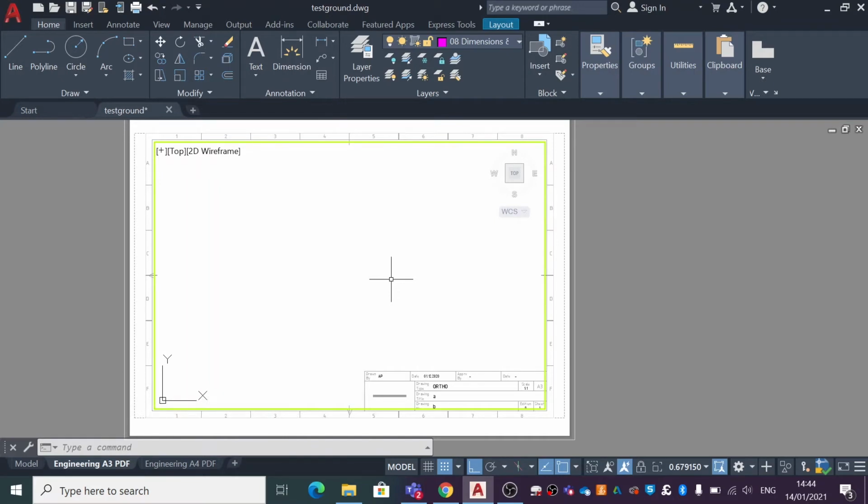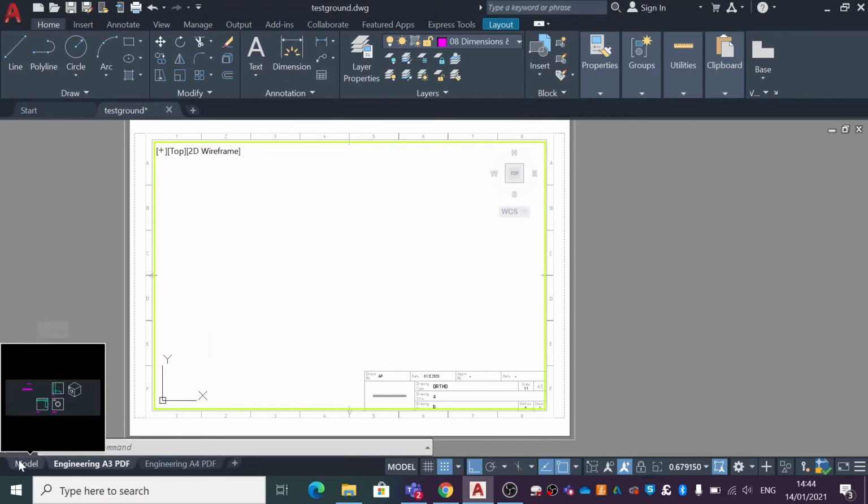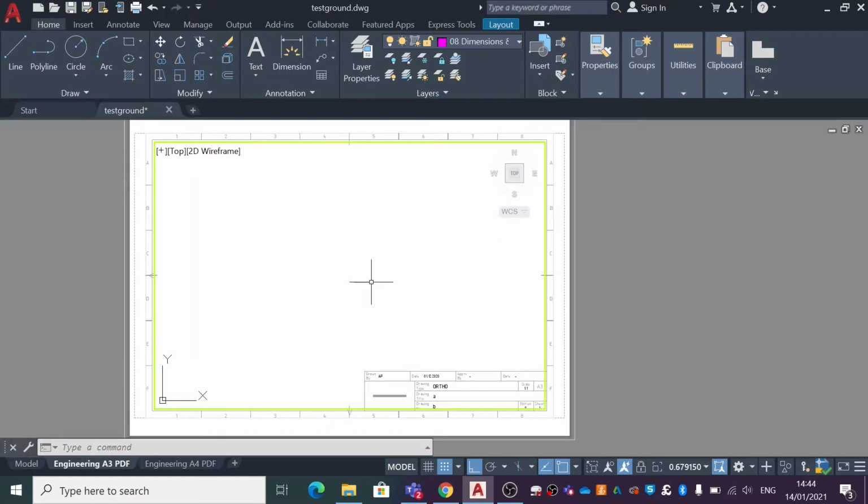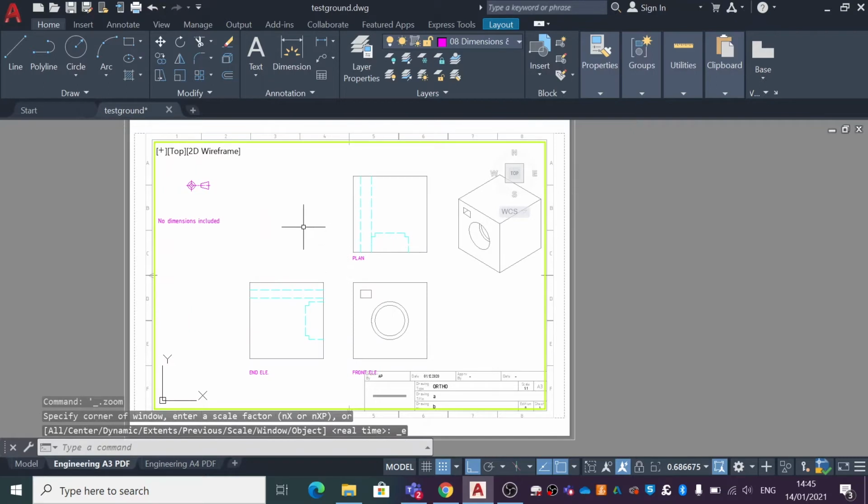Now when you're drawing things in the model space over here, that is an infinite space. Your viewport's an infinite space as well, so you may be tempted to try and pan around using the mouse wheel by pressing it down to look for your drawing, but you're not guaranteed you're going to find it that way. So how to get your drawing into the viewport is simple. You just click the mouse wheel a couple of times, and the program will search for the drawing that you've created and place it inside the viewport.